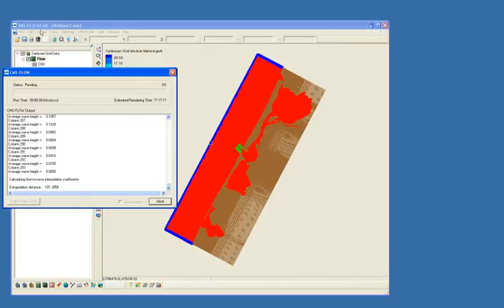If we did this from the other option, SMS would actually do all this mapping back and forth for you. So this will take just a second, but it's choosing the first 2 wave conditions. It will run those, and then it will actually run the flow model between those 2 times. So when the flow model is over for that hour, it'll run the 3rd wave and then run another flow period.